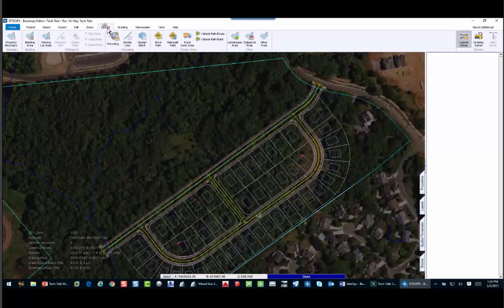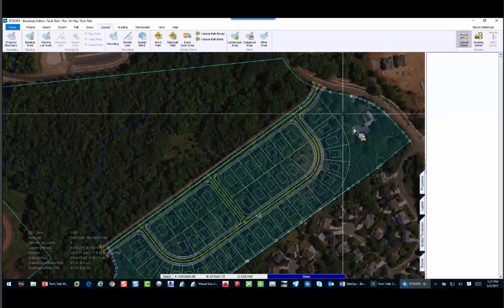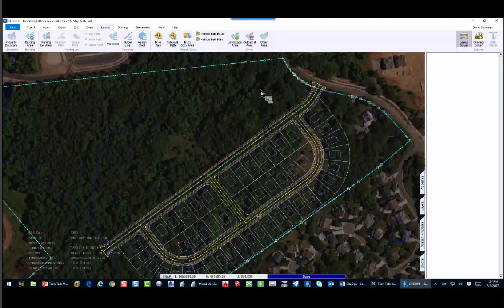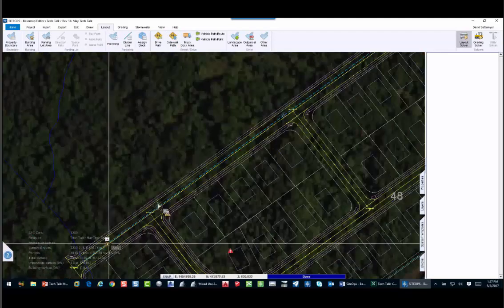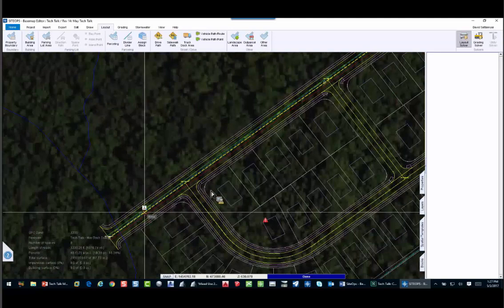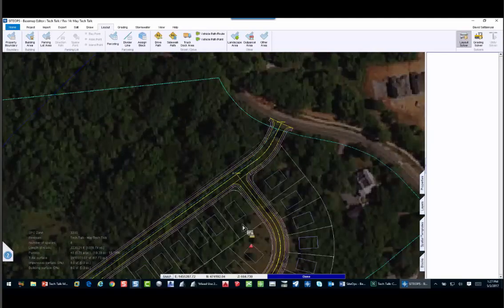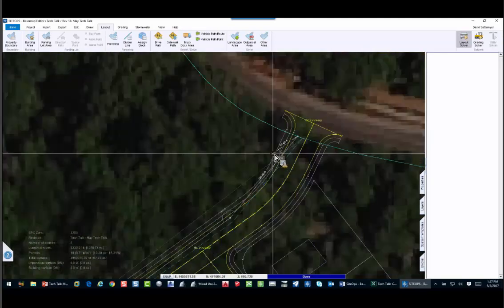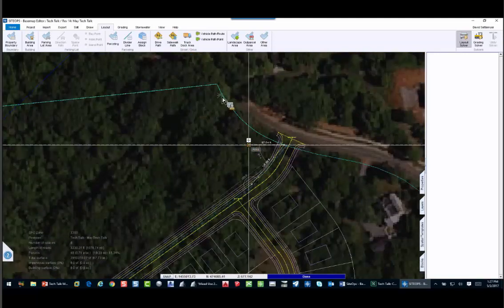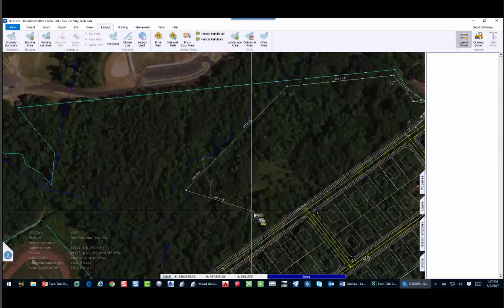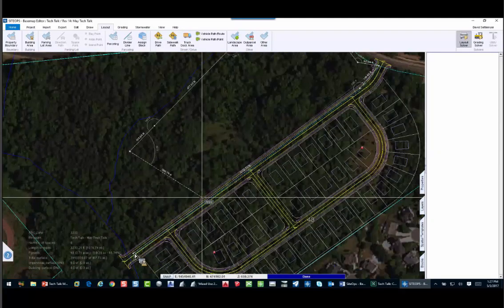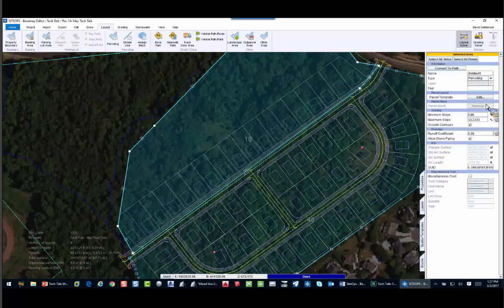Let's come in. At this point, instead of doing a chain, I'm just going to go in and draw something. I want to show you a difference as well. Because we noticed, even though that parcel area is way out to the edge, if I don't draw anything out there, it doesn't draw it. So in this case, I'm going to go to parcel, and I'm just going to come in, and let's just zoom into the roadway. Don't really want to overlap the other one very much. It's not a big deal if you do, but let's just come in, grab this. We'll just come along the edge because we don't want to buffer on the roadway. And let's just go in and do something like this. So now what I've done, create another parcel area. Again, so you can have as many of these as you want.